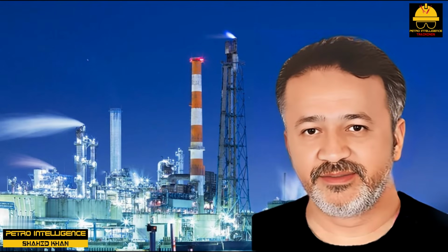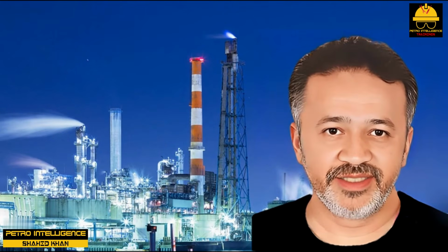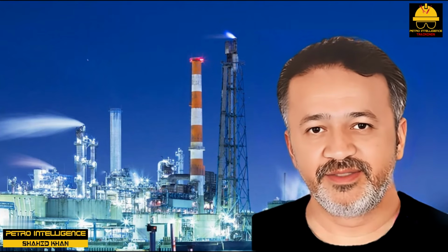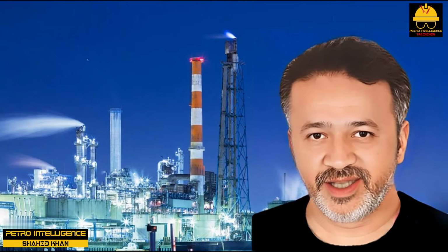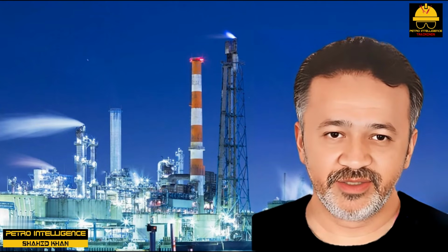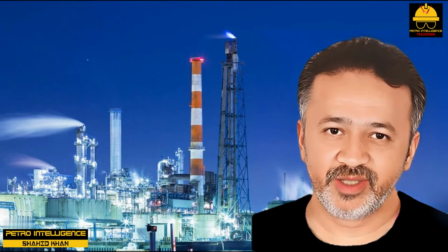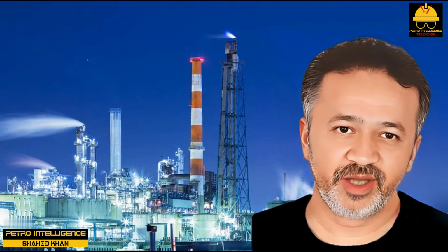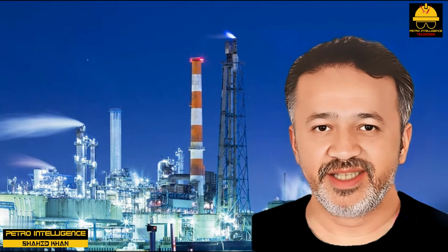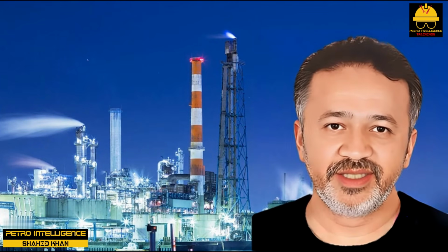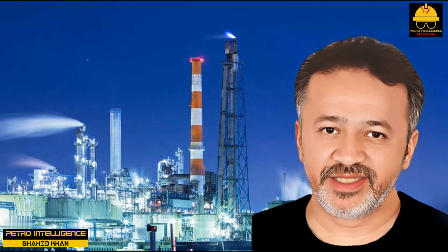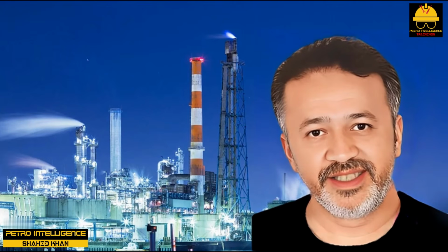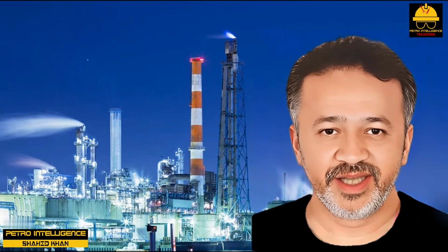Condenser operation. A closed-loop refrigerant condenser ought to be one of the cleanest services in a process plant. Even seal or lube oil leaks affect the evaporator efficiency rather than the condenser. I have measured rather high heat transfer coefficients, for example, 140 BTU per hour square feet degree F, in such condensers, even after that condenser has been in service for several years since its last cleaning. The most common problem with refrigeration condensers is condensate backup rather than fouling.